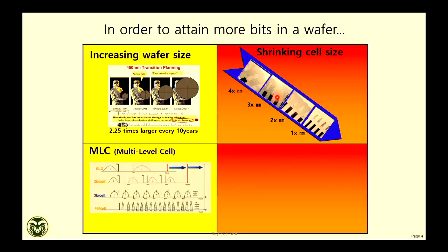The other option you have is to scale logically. Okay, I cannot make things smaller, but one cell can store multiple bits. So it's called logical scaling. And this is the physical scaling: you make things smaller so that in a given area or on a given wafer, you can pack more bits. Or another option is, my hardware remains the same, and I will logically scale. If you recall, we had assignments on multi-level cell, where one cell will store 2 bits. Similarly, one cell can store 3 bits, 4 bits,